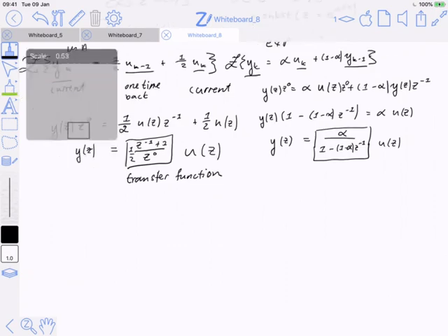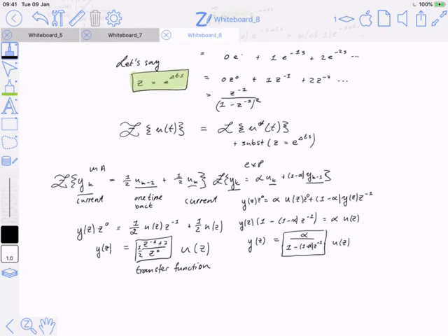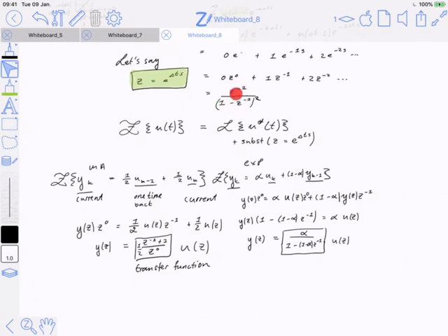So for instance, one of the inputs may be something like this, right? Here we have the Z transform of a ramp. And if I wanted to know what the moving average looks like when applied to a ramp, I would take this function over here, multiply it by that transfer function over there, and I would obtain a new function of Z, which would represent the filtered signal on the output.